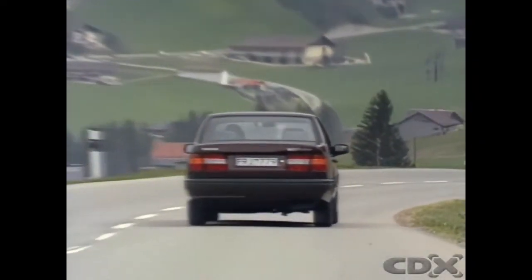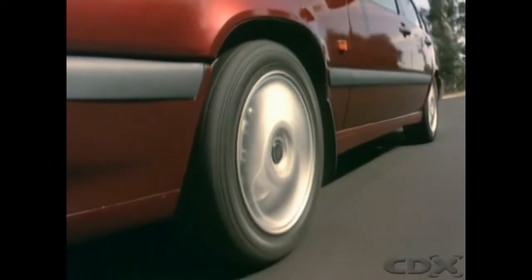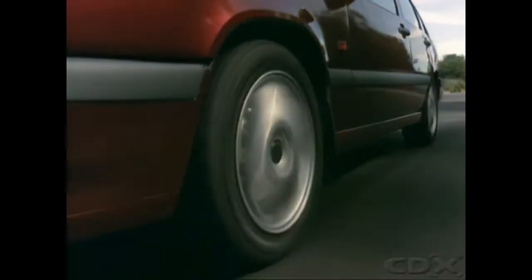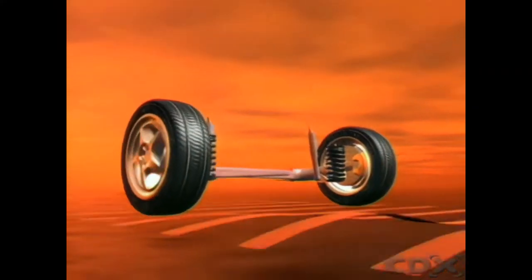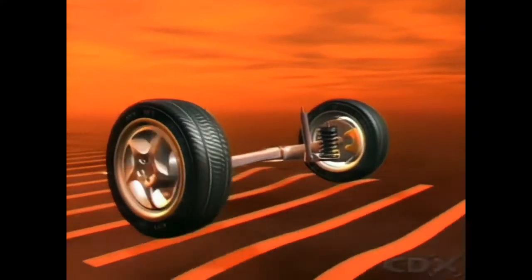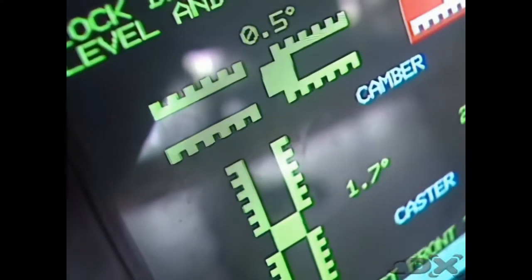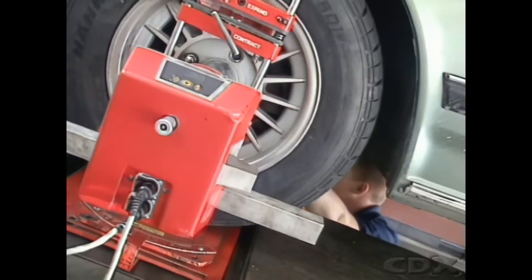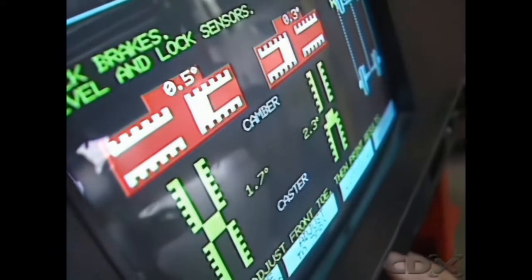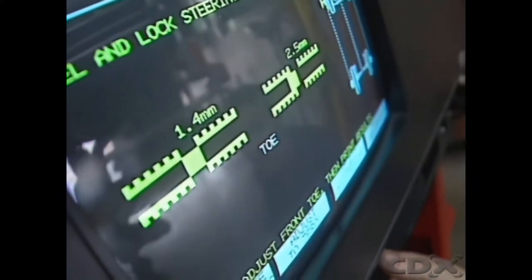One of the main benefits claimed for independent suspension is that unsprung mass can be kept low. Also, if a wheel on one side hits a road irregularity, it won't upset the wheel on the other side on the same axle. And it allows wheel camber to be adjusted individually when provided for by the manufacturer.